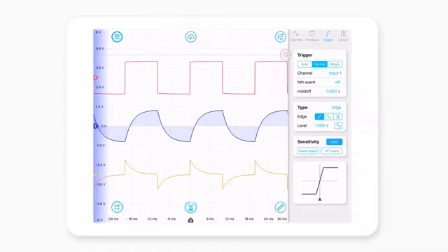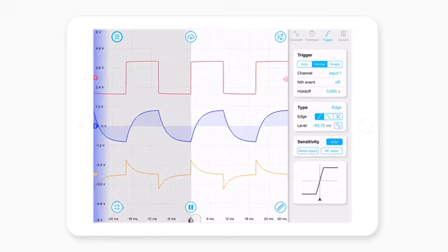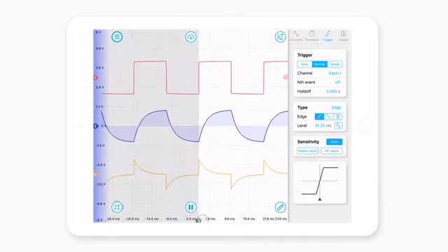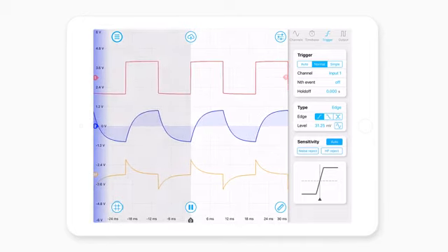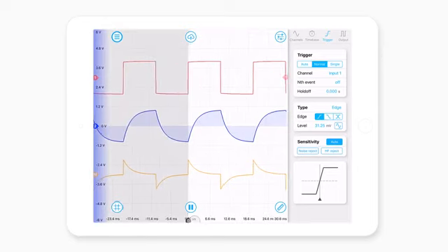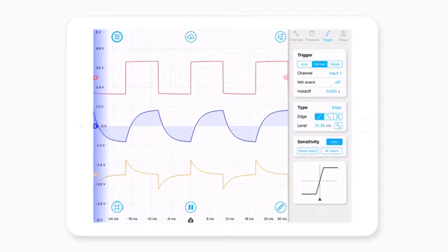So if I bring it down and then set it here, you'll notice that the hourglass has now disappeared and my oscilloscope is now triggering off this specific event at time 0. A few things to note here: the little teardrop here is called the trigger level, and the black teardrop on the horizontal axis is the trigger alignment. Basically, nominally, the signal will be triggered off at time 0 at whatever level we specify.